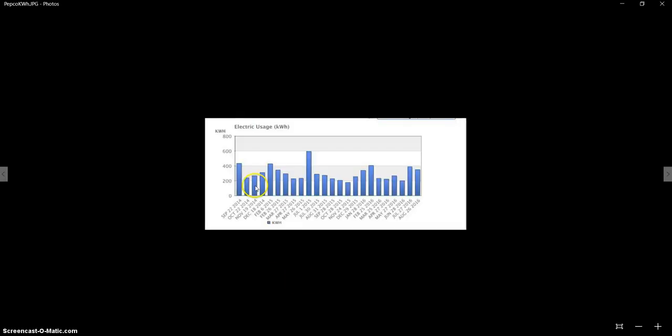So coming back to this, if 240 kilowatt hours is my average usage, you have to divide it by the hours, which is 30 days times 24 hours in a day. Instead of 24, I'm going to make it 8 because you really are not actively using it across those hours. So 30 times 8 is 240. So my usage is a little higher than 1 kilowatt.